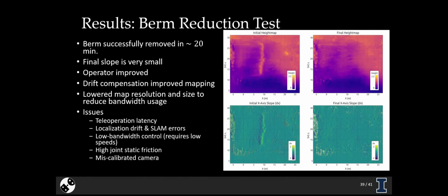Another thing to mention is the operator got significantly better over the course of this. Initially, they were driving a little bit fast, perhaps, and it just takes time to use the system. And again, this comes back to the fact that the CTL has a lot of oscillations about this pitch axis. Additionally, the controllers themselves were tuned to have fairly good position tracking in a stationary state. And so when we go to start moving, there were cases where we get big steps and some oscillations would occur. So there's improvements that could be made on the tuning side of things as well. But fundamentally, the control is really limited.